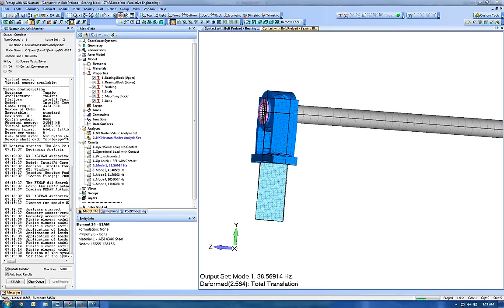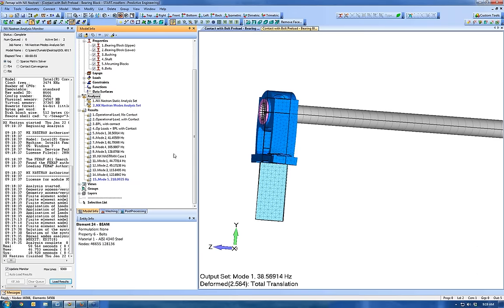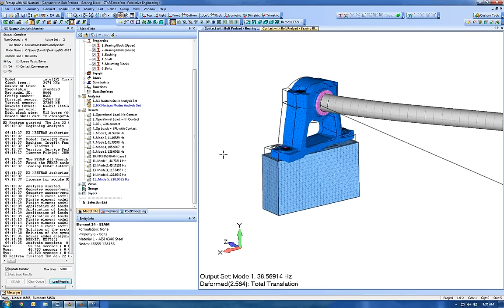Hi, Adrian. Just a few questions. Are you using the iterative solver when you're using the contact sequence? Oh, yeah, I think you are. Probably the way this one's running, I did not turn that on. It would probably be significantly quicker if I did. Well, it might not. It's a mixed bag of contacts. It's always tough to tell, especially with rigid links and beams. I don't know. That's why I build small models and try to debug all the mechanisms quickly before doing something really big.